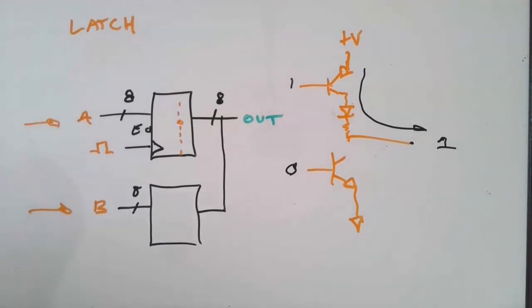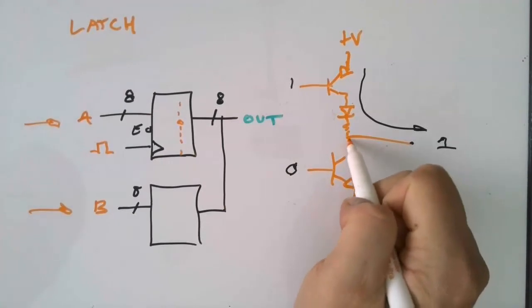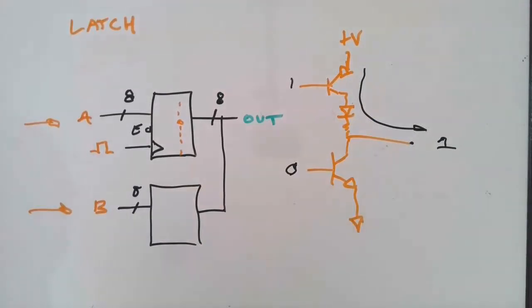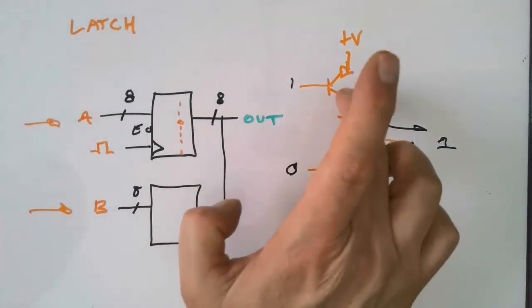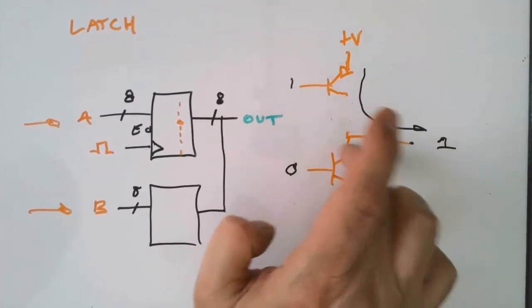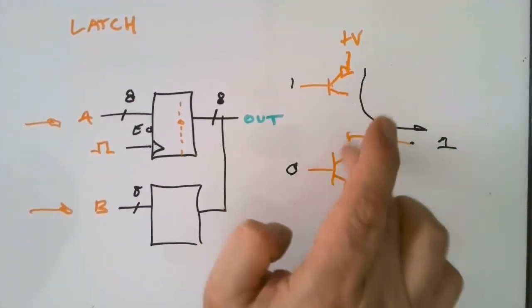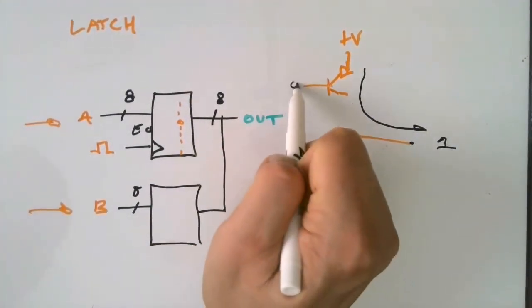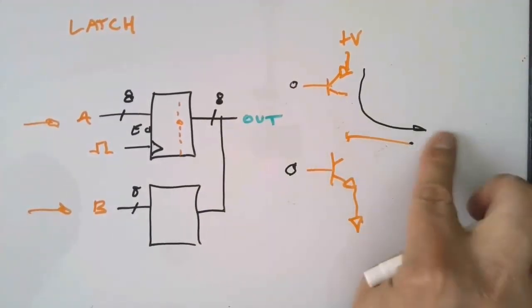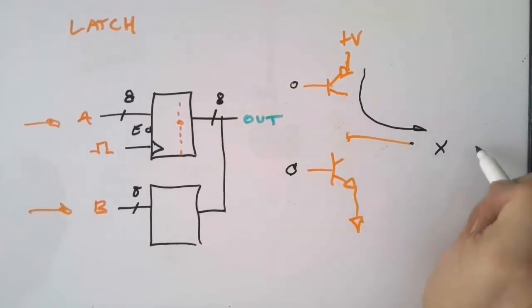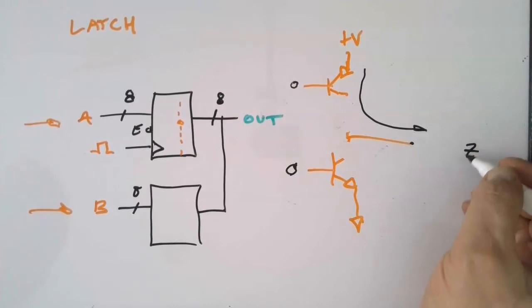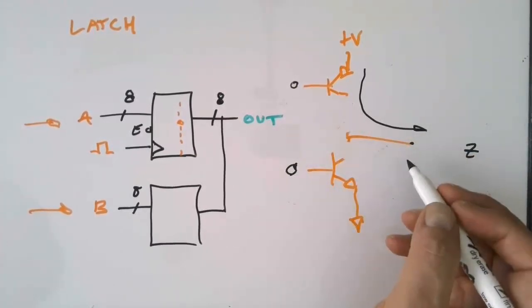And so far on all the logic devices we've talked about, only one transistor can be on at a time. If you turned on both transistors, you could damage the output. That would never happen. However, what if we could turn off both transistors? What would our output look like? Well, it would literally be floating if both transistors were off at the same time. You think, well, that doesn't sound good. That's not a 0 or a 1. And sometimes they'll call that an X or a Z, not usually X, that's don't care, but a high Z output, which means it's floating.